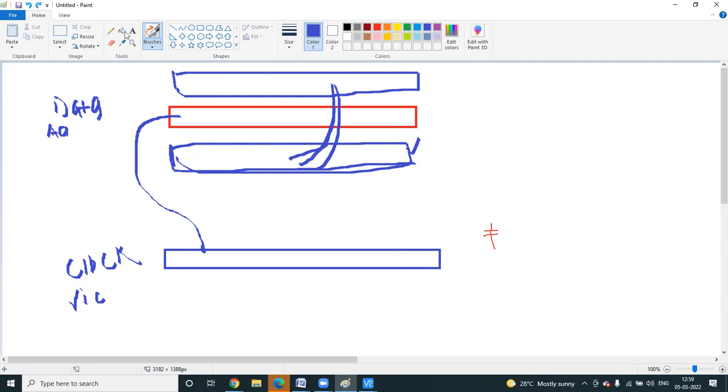Okay, and which type of shielding? See, if it is more critical, go for coaxial. This you need to ask the designer. When you do shielding, which shielding you need to do, you need to ask the analog design people, because they can tell even the voltage thing. This is not our role. They will tell you this is a critical signal, then you can tell I will do coaxial shielding.